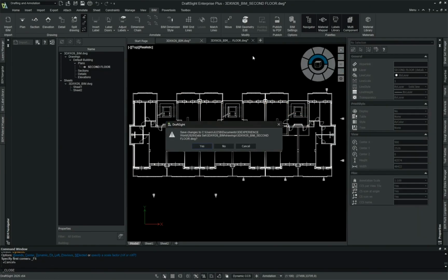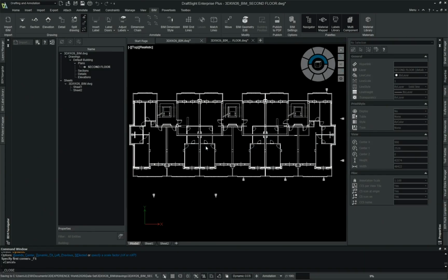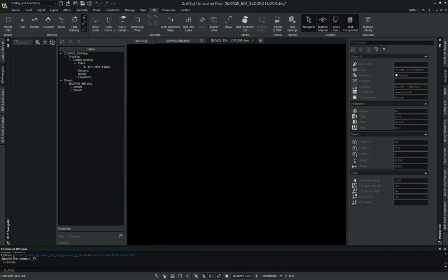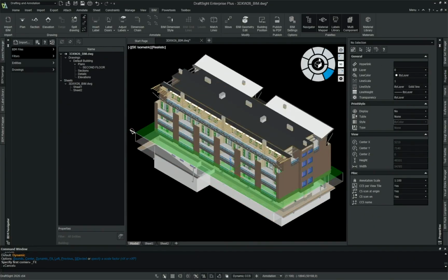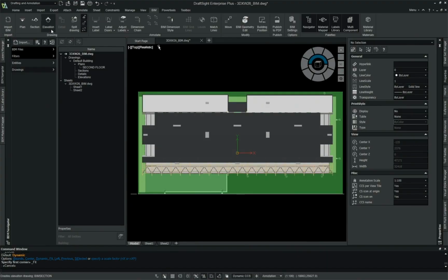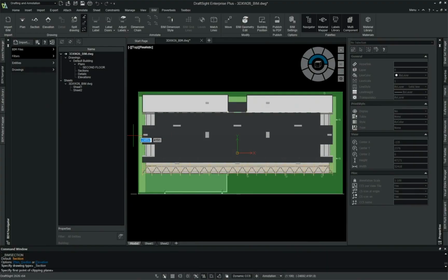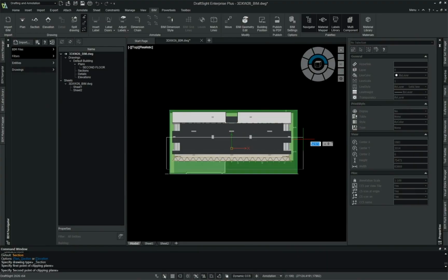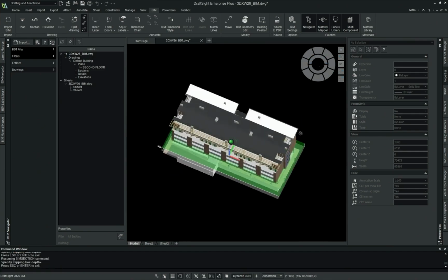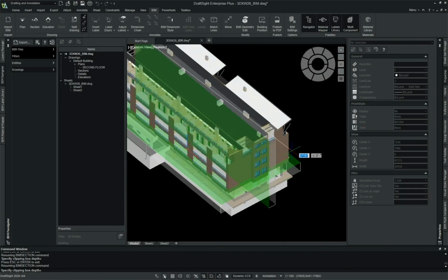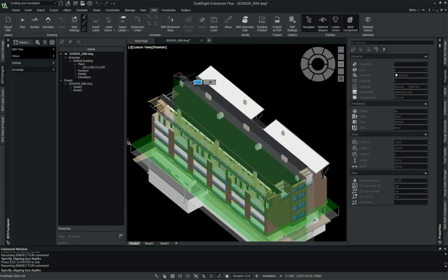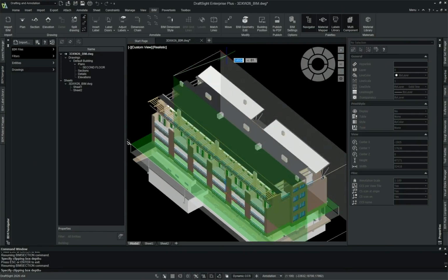Okay. So I'm going to close this out. I'm going to make maybe one or two more floor plans, and then actually I'll do a section first, and then I'll jump over to the annotations next. So again, the section follows the same philosophy here. You make your cut, and then you specify your depth that you want to actually see. So I'm going to just do it through the whole building.